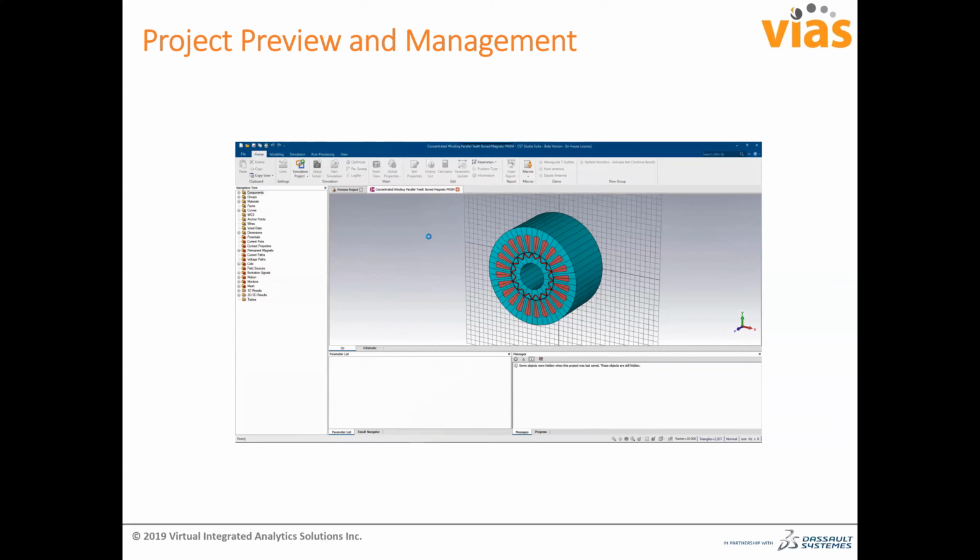So the benefit of doing this is when you have a very big model which takes a long time to open in the CST environment, meaning a very complex model. Let us take a tank, an army tank, which is a very complex model, and it takes time to load up in the CST GUI. Then you can have a preview of which solver I have used and what the mesh cell was, and if you need to change the solver or do some editing, then you can open that in full mode in CST and do the further analysis. So this is the project preview and management feature which has been added in CST 2020.